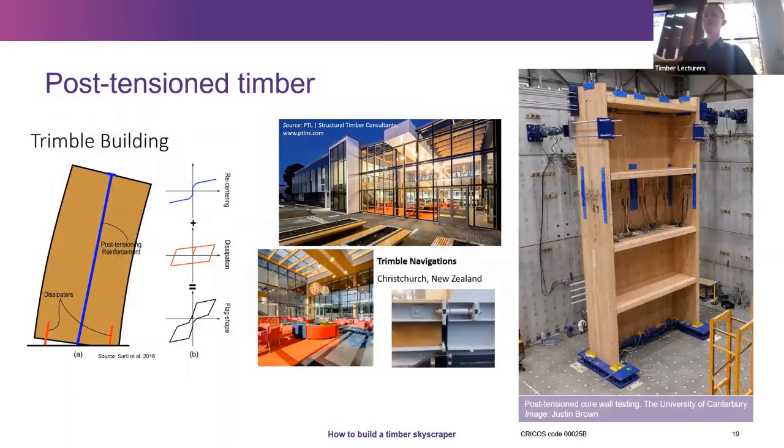This is something that comes from the Kiwis across the ditch. They've explored post-tension timber for seismic applications. In the corner there, that big wall structure, one of my friends, Justin Brown, did that while I was doing a PhD in New Zealand. He started a little bit after me, and he built that tall timber tower, which is post-tension, similar to post-tension concrete. You can imagine it's like a rubber band that goes through a hollow part in the timber, and then you pre-stress it a little bit.